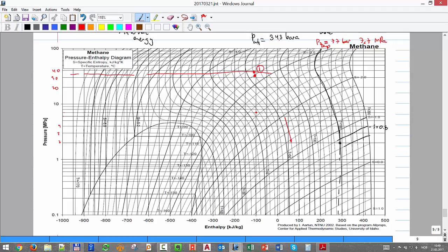And I know the thermodynamic process across the choke is isenthalpic. Okay, that means that the h of that point should be equal to the h, not h in years, but the h in enthalpy. So those two should be the same. So it goes vertically during the expansion up to that point, and there you see what temperature reduction you got. The first one was 70, and now this temperature will be more or less like 15 degrees Celsius.